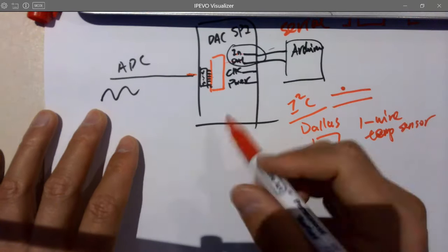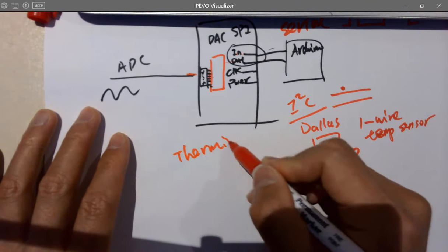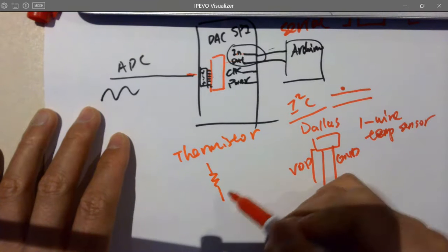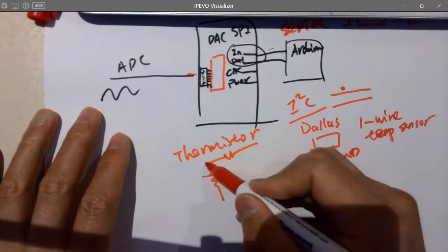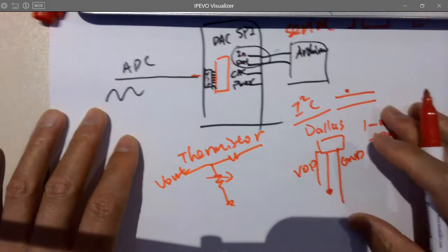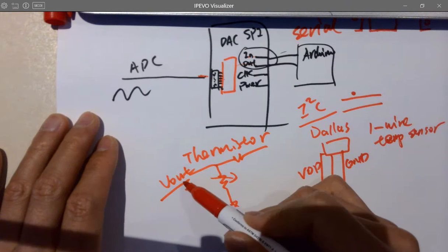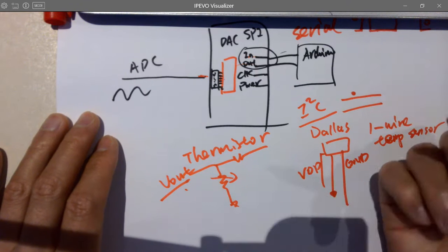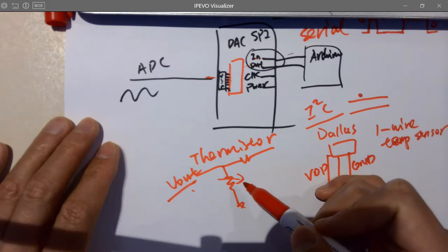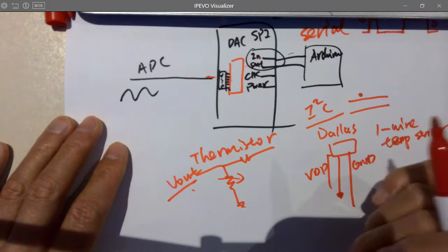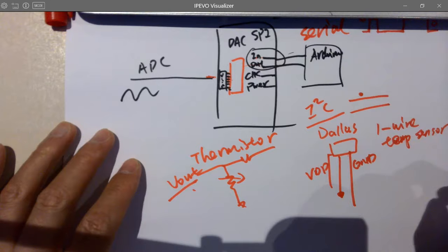That's awesome. In the past, there are some other temperature sensors like thermistors, right? It's a resistor that senses temperature and changes resistance. So if you have a voltage divider here, here's a VL. You can detect the variation of the resistance by detecting VL to find out the resistance. There will be an equation to calculate it. The advantage of this one is it's very cheap, right? For $1 you can buy probably 20 of them. Temperature sensors, it's pretty good actually. Not that accurate, but very cheap, very small.